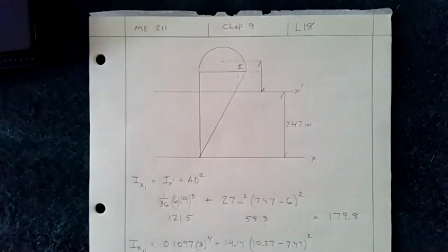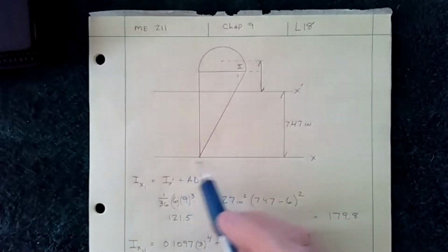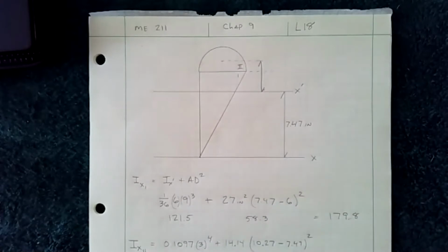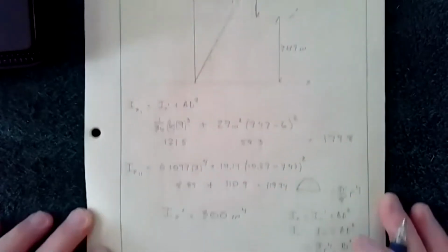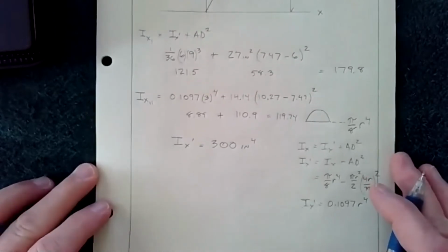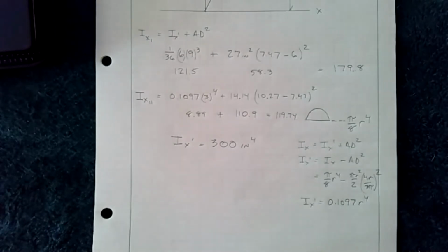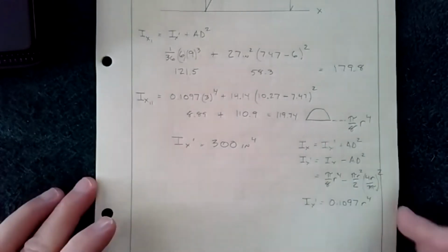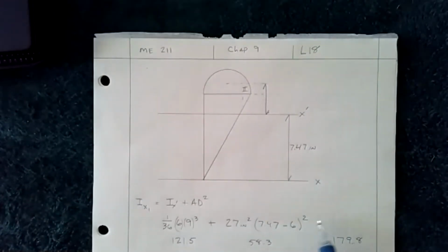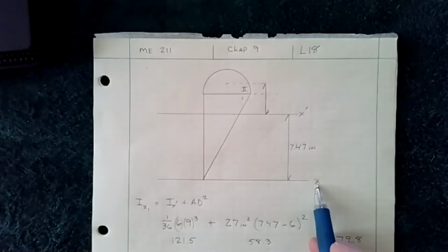I'm not going to give you anything more complicated than this in terms of geometries. Usually even on the final, we might add maybe a quarter circle or a square with some circles cut out. But the idea you have to remember, and this is the big takeaway from this, is if you're doing a moment of inertia, you have to go from the centroid of the shape to the axis of your rotation. And sometimes they may just ask you, in this example, it could have been find the moment of inertia about the x-axis.